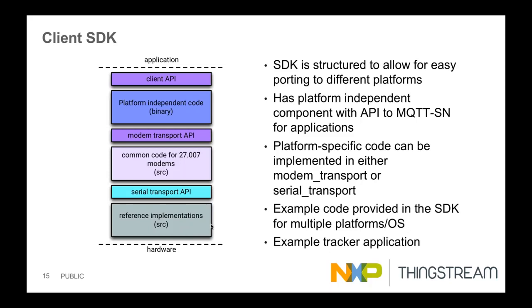And the serial transport gives you the ability to provide your own implementation below that, which decides which UART you're going to use, sets up the UART properties and parameters, and sets up any power considerations you've got to think about, all of that stuff. So that's the real low-level implementation.